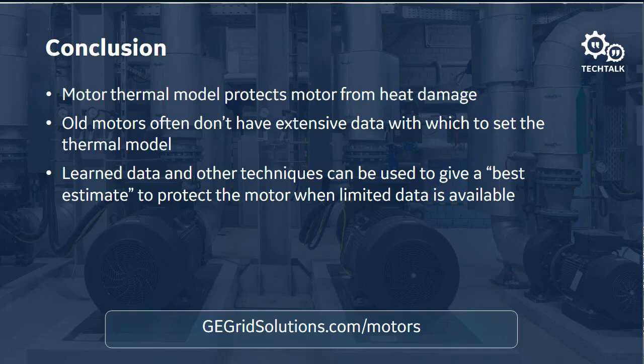What you set your overload at in the nominal state becomes more of an art than a science for the protection of the motor. When you allow the overload to go larger, you are allowing your process to overload the motor, which in most instances is acceptable. Now, that service factor is not meant for continuous operation.